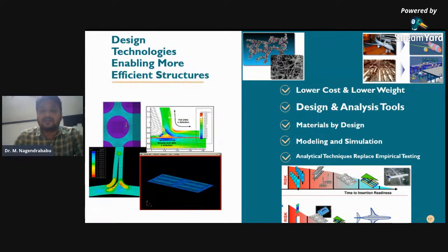So as I told you earlier, I'm going to discuss a little bit the new material landscapes. That is the main important theme of this particular FDP. Standard aerospace aluminum, something like 6061, 7050, and 7075. And traditional aerospace materials, nickel 718, titanium 6Al-4V, and stainless 15-5PH, I guess, still have applications in aerospace. These metals, however, are currently ceding territory to new alloys designed to improve cost and performance. To be clear, these new materials aren't always new. Some have been around for decades.